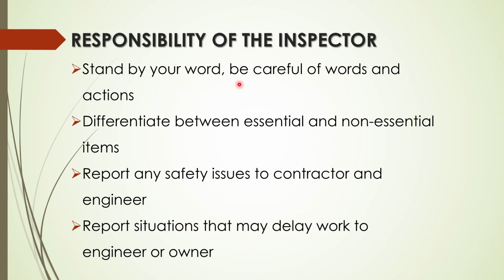Stand by your word, be careful of words and actions. Differentiate between essential and non-essential items. What's critical at that time? Don't be testing the foundations way on the backside of the site when they're not even close to placing concrete, versus where they're ready to place footings and you haven't tested the foundation yet and the concrete truck's sitting there. So itemize your ideas.